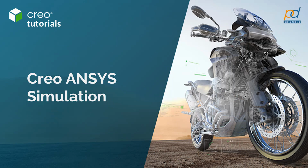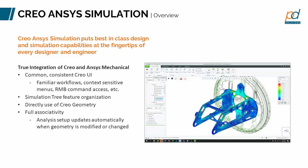Okay, Creo Ansys. This is the most recent of the new products. As the name suggests, this is jointly developed with the Ansys company, and it's essentially a kind of light version of Ansys Mechanical integrated with Creo. If you know Ansys, you'll know that it comes at 3 levels: Pro, Premium, and Enterprise. This is more or less Ansys Mechanical Pro, but integrated into Creo.